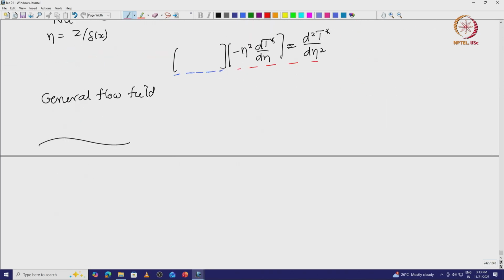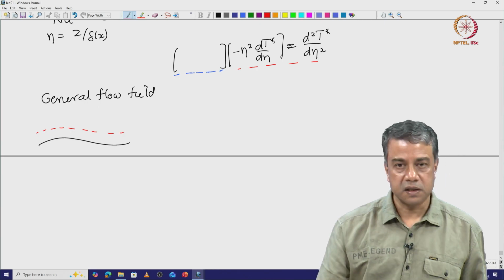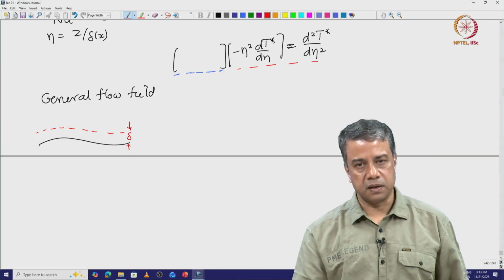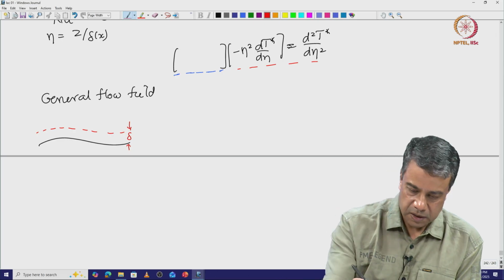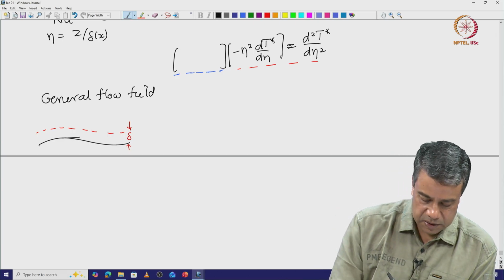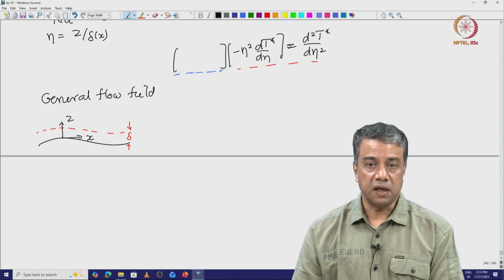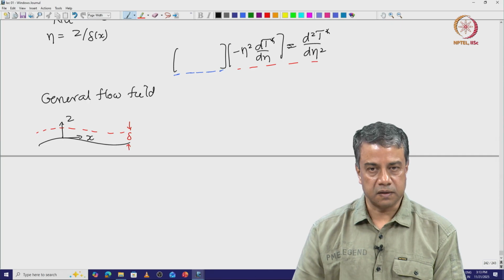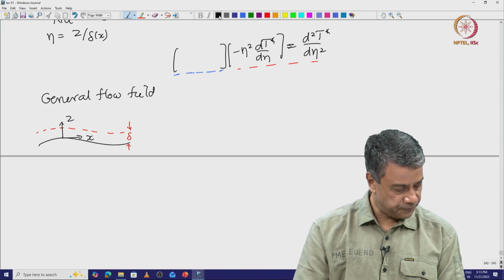so that within the boundary layer it is effectively like the flow past a flat plate. So, in this case as well I will assume that the boundary layer thickness is small compared to the radius of curvature of the variation. And locally I can impose a coordinate system x and z. X is the streamwise direction, z is the cross stream direction. In general these variations could be 3 dimensional as they were in the case of the flow past a sphere. I will restrict attention to 2 dimensional variations.